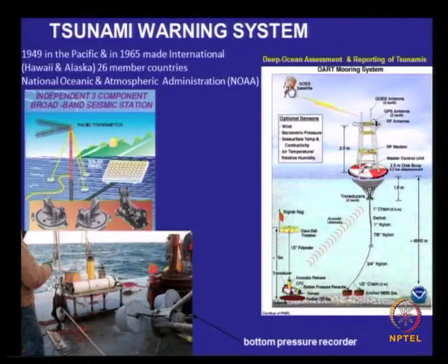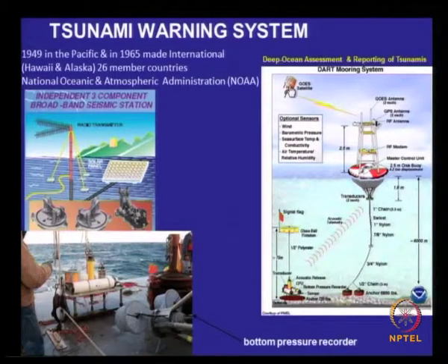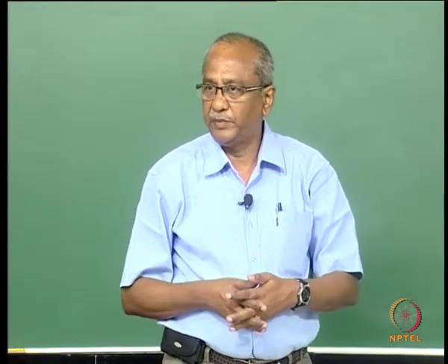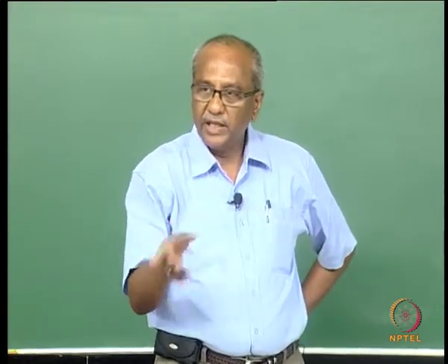So for waves moving for about 30 seconds, you know the order of pressure that the pressure sensor near the seabed should read for that given water depth. You know what the maximum pressure should be for a given water depth, but if it exceeds that pressure, then naturally you can easily suspect that something is going wrong, maybe a tsunami or something of this very long period has started propagating, and immediately this.